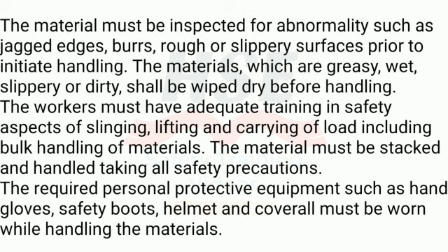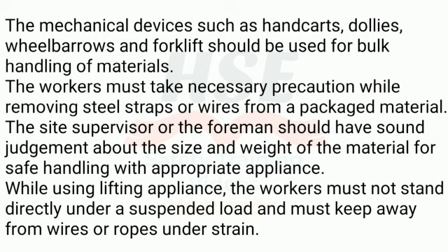The workers must have adequate training in safety aspects of slinging, lifting and carrying of load including bulk handling of materials. The material must be stacked and handled taking all safety precautions. The required personal protective equipment such as hand gloves, safety boots, helmet and coverall must be worn while handling the materials. The mechanical devices such as hand guards, dollies, wheelbarrows and forklift should be used for bulk handling of materials. The workers must take necessary precaution while removing steel straps or wires from a packaged material.